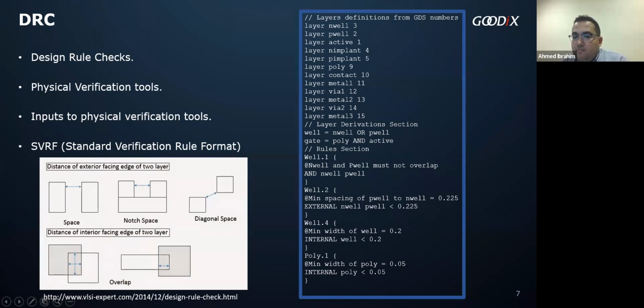Okay, so the first answer was the introduction of design rules and their checks. The design rule defines the fabrication requirements of a particular process at a given foundry, of course. So design rule checks were used to confirm that a design satisfied minimal constraints of geometry and to help users determine which drawn layers represented which masks.